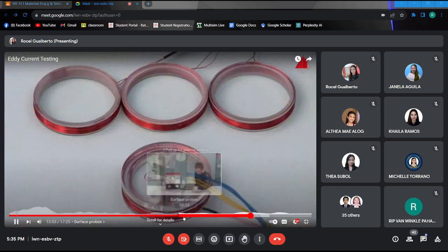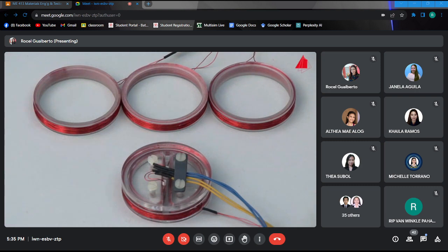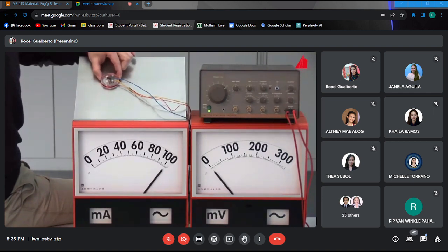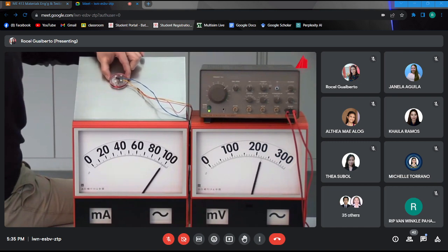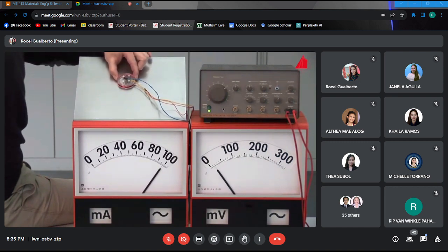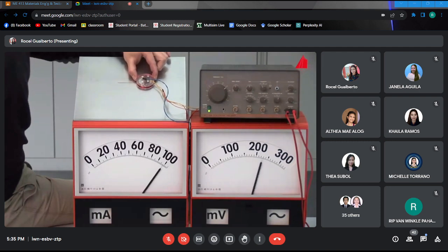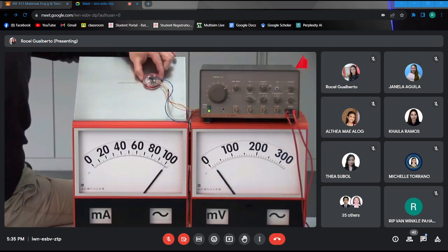Now we use a trick that we have already applied to the coaxial probes. We switch the receiver coils against each other and only measure the voltage difference between them. Now everything works in a way that suits us. Small voltage difference in the intact sheet, strong voltage fluctuations at the left side of the saw cut, and at the right side. But one point should always be kept in mind.